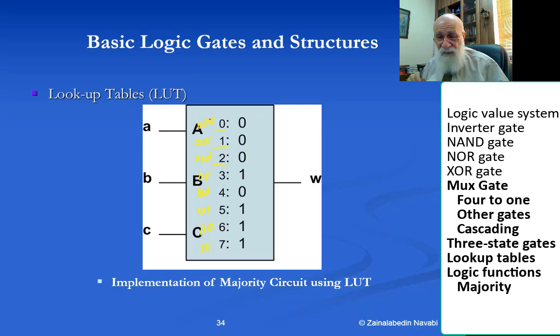These are the addresses, these are the decimal values for the addresses, and in these addresses there are these values stored. What it means is I can turn this lookup table into whatever 3-variable function I want. Since FPGAs use that very often, we in a way look at it as a logic structure, or a programmable logic structure.